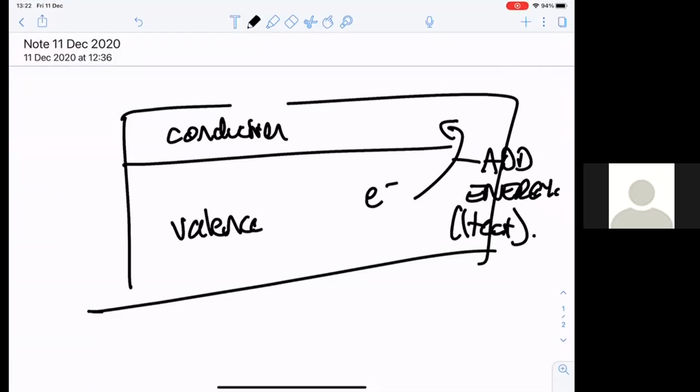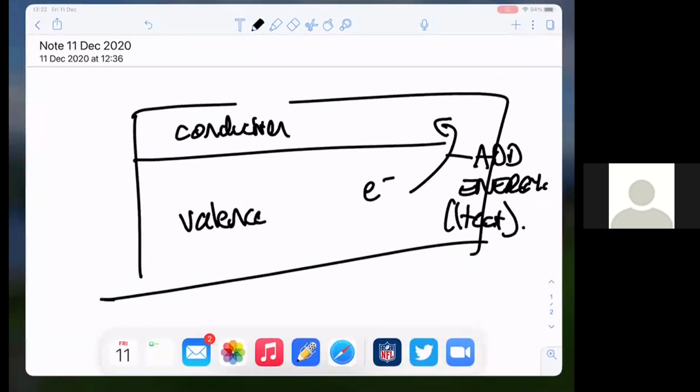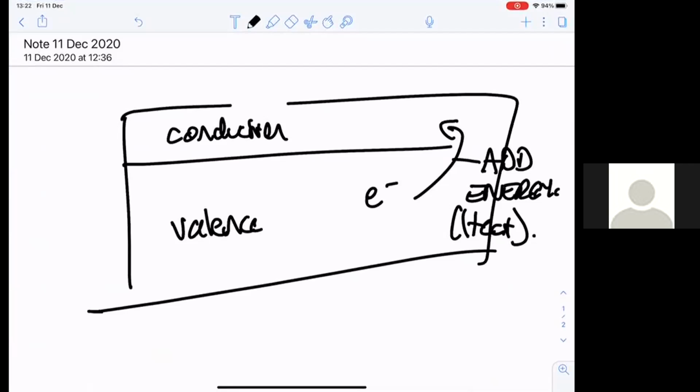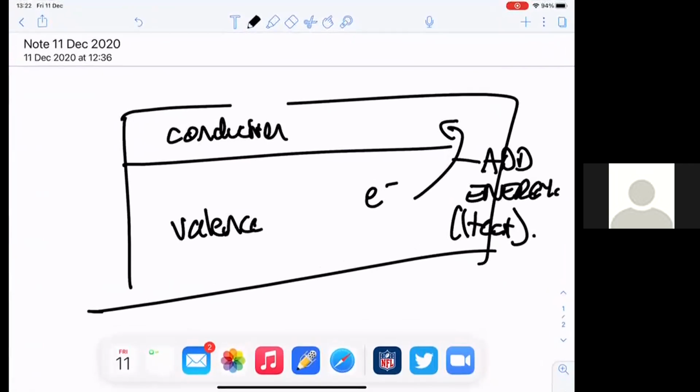Isn't it? So actually this is your fundamental basis of why those temperature graphs are the way they are. And actually this is sort of a penny drop moment. I'd be thinking about it backwards. Understand the difference between a conductor and a semiconductor, and those graphs will make sense when you get outside temperature. So the true statement would be, in conductors, resistance is generally proportional to temperature.